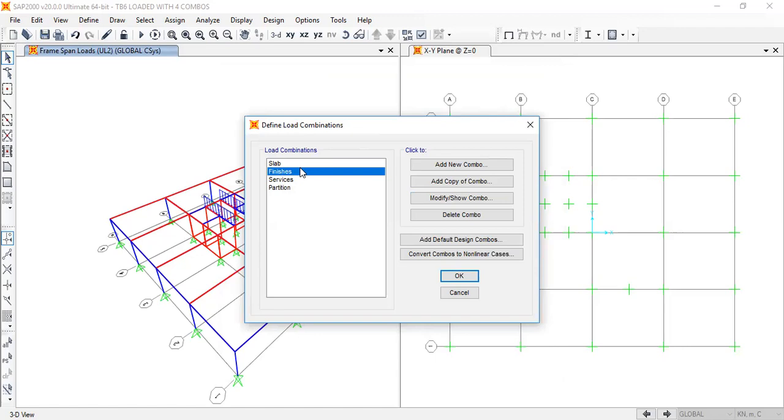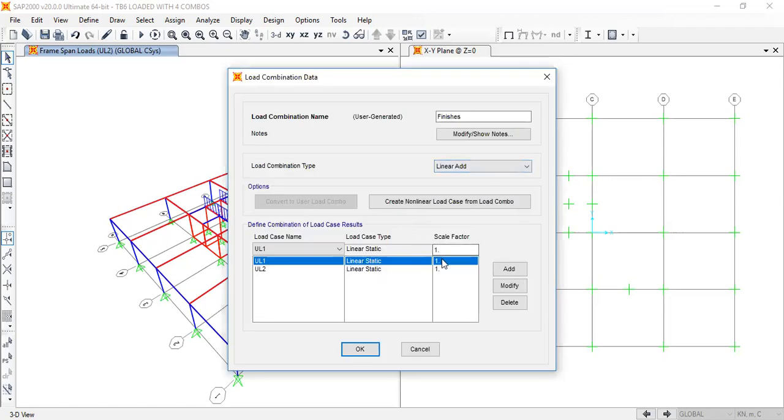okay, so for the finishes, I will use this one, right? Modify. So finishes, I will use 1 and 1 for both, because we usually use cement rendering, which is 0.5 kilonewtons per meter squared, and with additional tiles and everything, it's safe to assume around 1, and that's why I use 1, right?